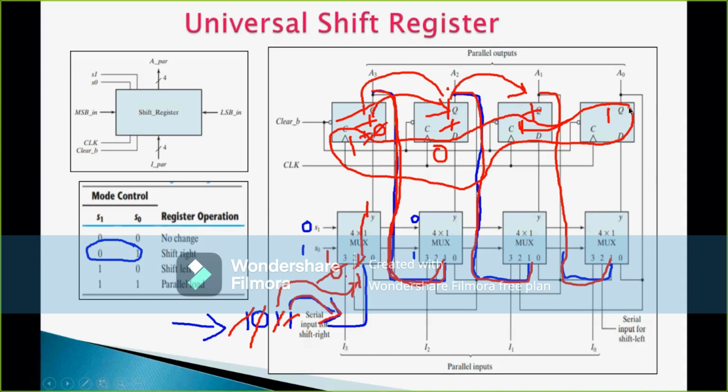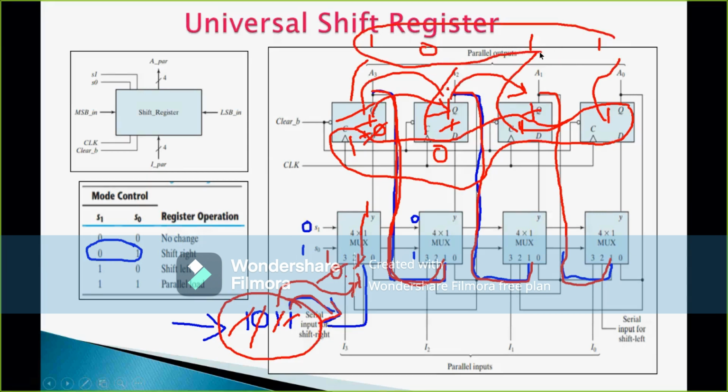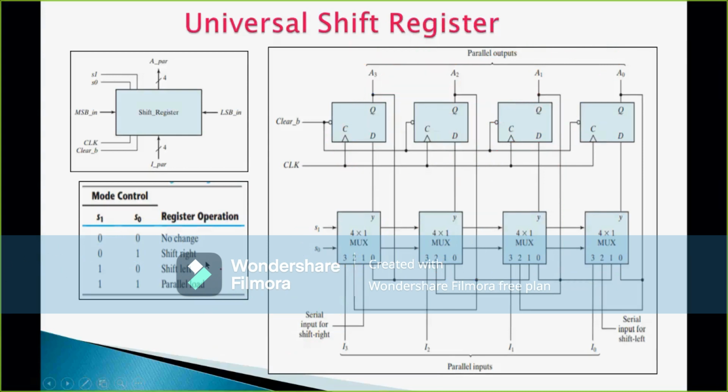This only you wanted to pass through this circuit, no? So that 1 0 1 1. Now you need to get this output in parallel, meaning through this line you can take it out. This 1, this 0, you can take it through this. This 1 you can take it through this. So finally 1 0 1 1. This only I decided to give now. But what shifting I performed here? Shift right I performed. So this is the scenario now.